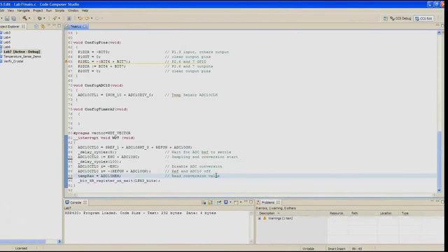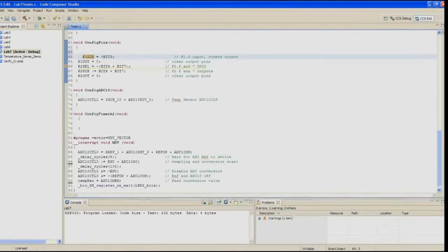In step 10, we need to change the transmit and receive pins. That's port 1, pin 1, and port 1, pin 2. If you're looking at the board, you can see those labeled on the silkscreen on the MSP430. From GPIO to the Timer A0 function, add the first line as shown below in the workbook to your config pins function, and then change the second line as shown.